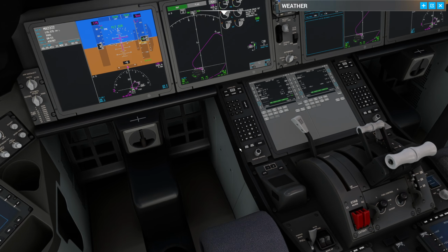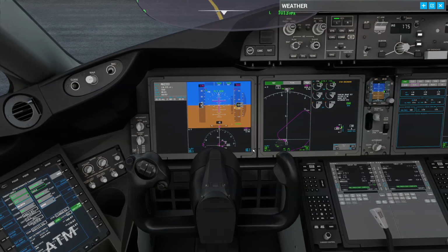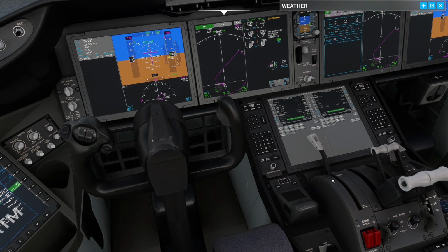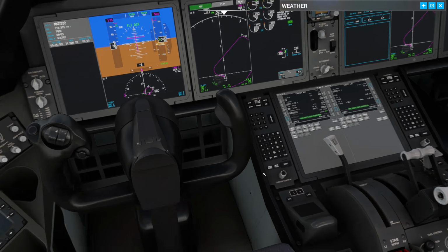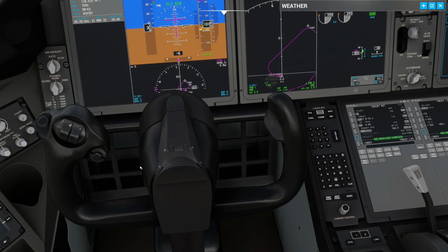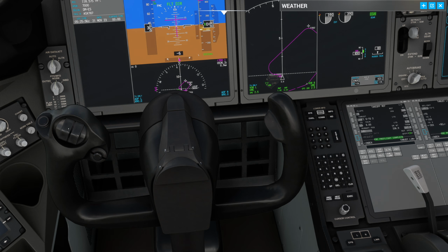Now, it occurred to me that in my last video I mentioned this, and people coming from the Airbus may not be used to what I'm talking about. In the Airbus, to set the takeoff trim, we would of course look down here, and there was a wheel that we would just set to the right number. How do we do it on the 787? Well, you need to have trim assigned. It's actually these little rocker switches.